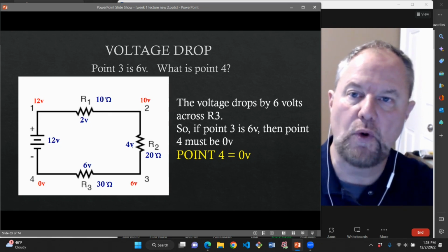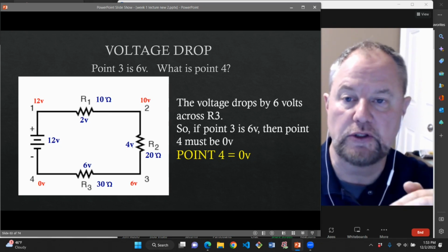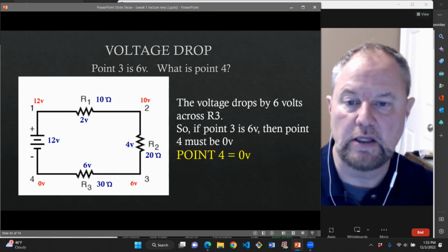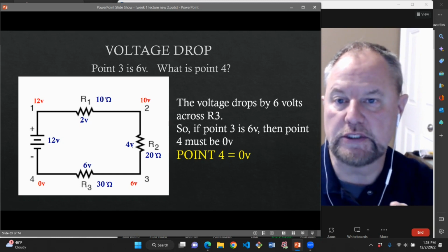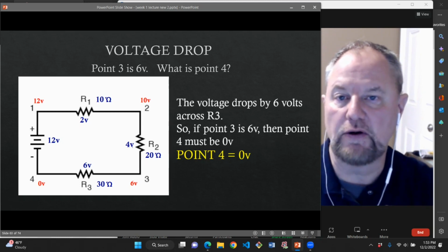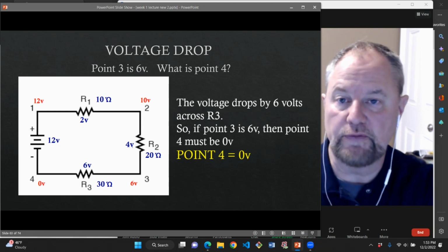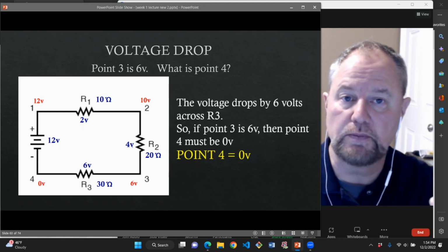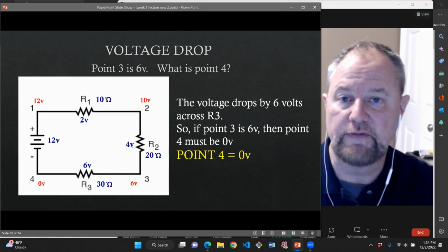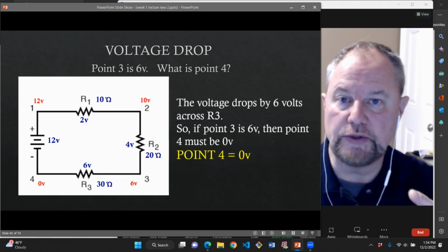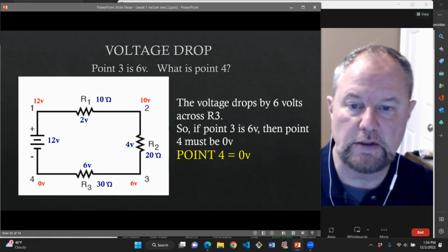At any different point in that circuit, you can observe and read a different voltage reading than what the power supply is providing. And oftentimes you will use resistors in this way to create a smaller voltage from the original power supply. Let's say you're hooking up to a 12 volt battery, but you need to power a circuit that only runs off of 5 volts. Well, you can divide up that voltage to get the voltage you need, picking the right resistors for the job.